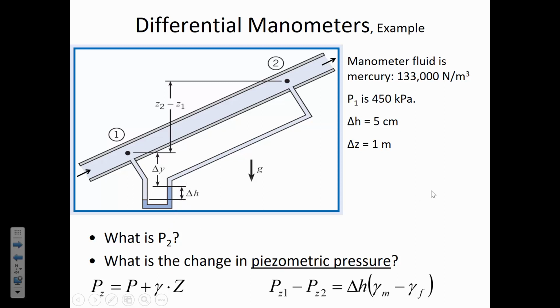So we're going to use the hydrostatic equation through this tube where static conditions exist to tell us the pressure at 2. We won't apply the hydrostatic equation through the pipe section because inside the pipe water is moving and it doesn't apply. The hydrostatic equation won't get you from 1 to 2 the direct route, but we can go through here where we have static conditions. So any questions so far before I start putting the calculations for that up on the whiteboard?